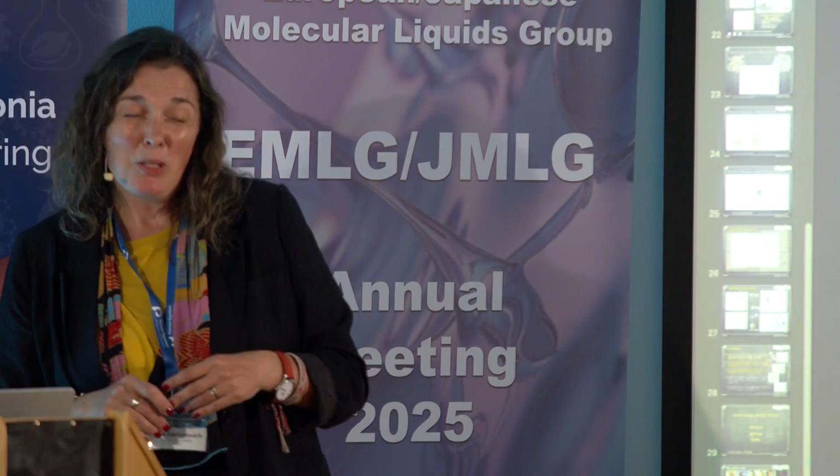Yes. So you need to find a magnetic material whose Curie temperature is far away from any heating range you're working at. If you get a transition from a ferromagnet, say, or an anti-ferromagnet, anti-ferrimagnet, anything with a remanence, to something that becomes superparamagnetic, so you destroy the spin ordering, you're screwed.